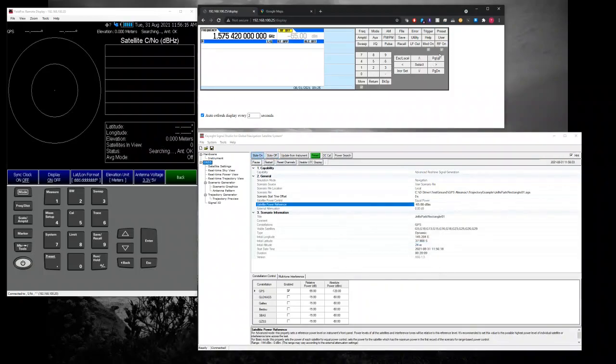And then we just have to make sure that the RF is on. Then we check on our receiver here, to see whether it will lock down the simulated location. One thing I learned throughout this trial is that normally, if you want to get a faster lock on locations, I would suggest turning the power up a bit high here. So we just wait for a while.